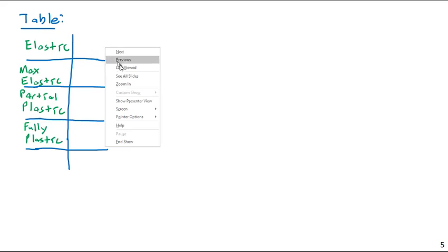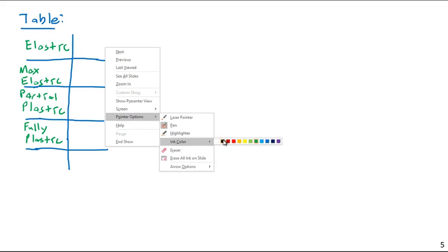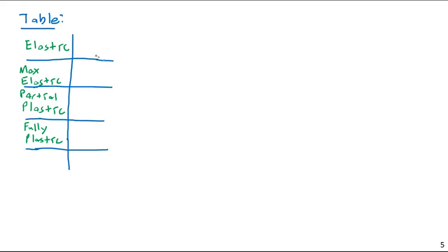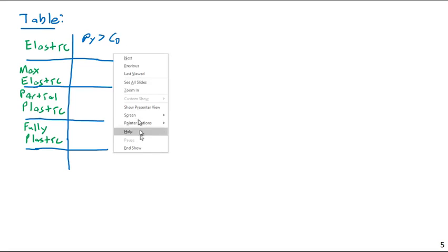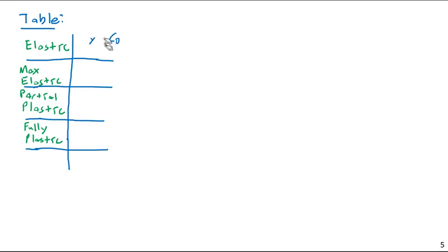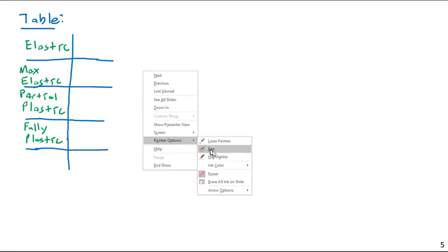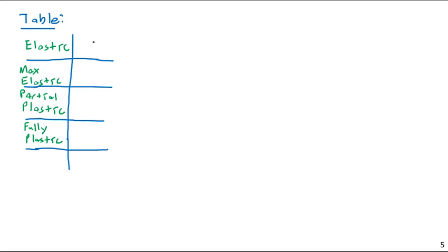So the elastic is what we've been dealing with before in terms of previous lectures, where the yield radius is actually greater than the outer radius. In other words, we don't have any portion of the cross-section in yielding. Everything is simply contained within the elastic stress region. So that's nice and friendly. Everything's just nice and simple, linear. We don't have to deal with any plastic problems. And gamma max is less than the yield strain.